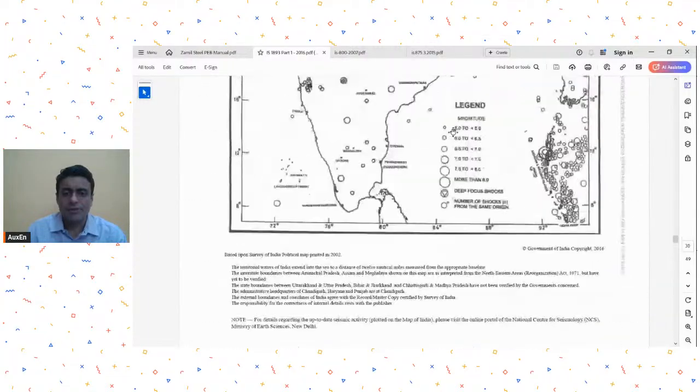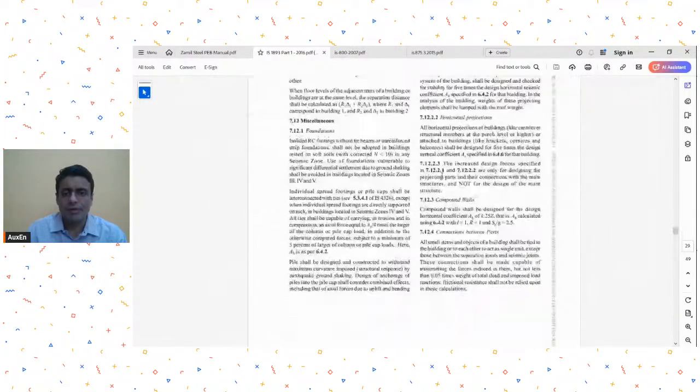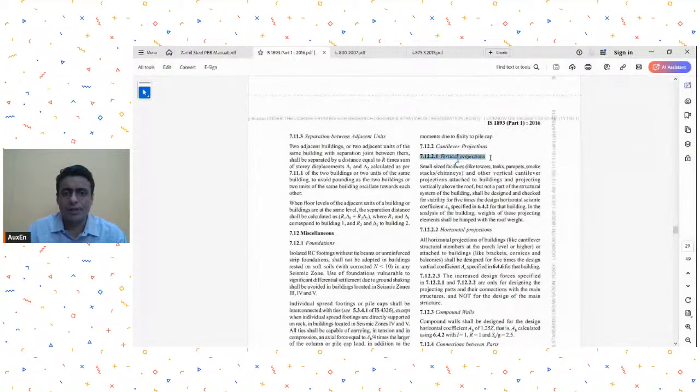So 5 times the vertical earthquake means, because we have defined the response spectrum in Z function right now, what you will do? Now you can make a load combination, and that load combination may look like something like this. You can probably make a 5 times response spectrum in Z and whatever other load combination factors you have.